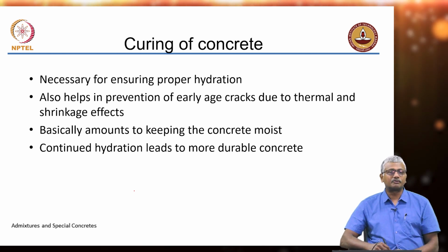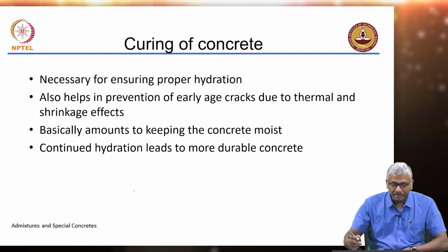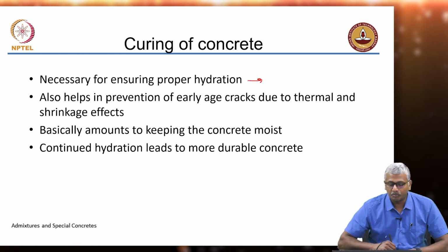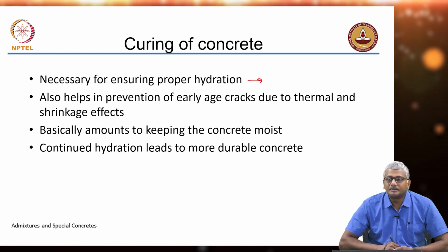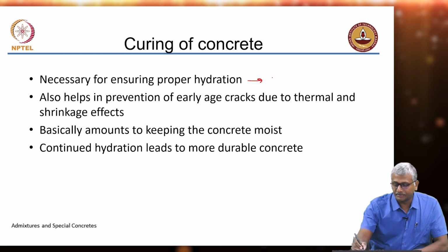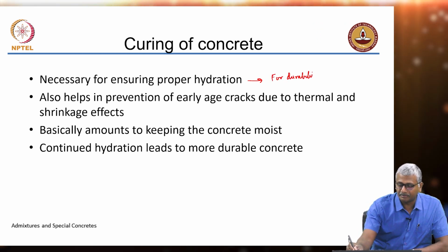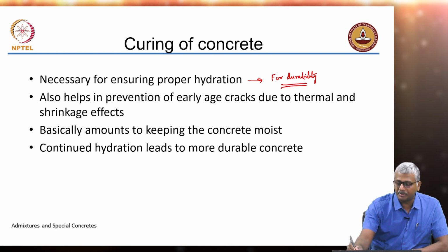And of course, curing of concrete is important to obtain the required level of hydration, but curing is done not so much for strength, but more for durability. Always remember that curing is important for durability.